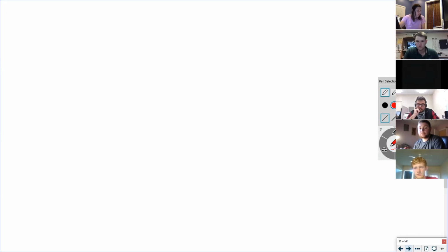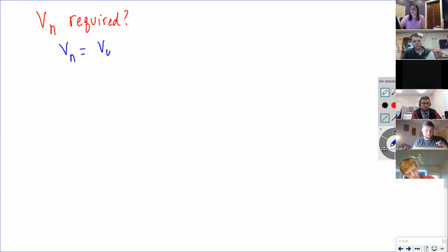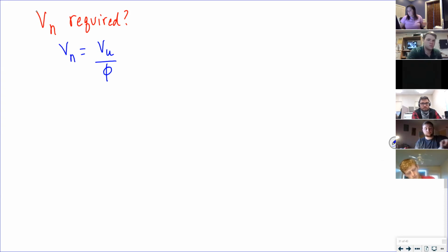So how much nominal capacity do we need? Vn equals Vu over phi, 105 kips over phi.